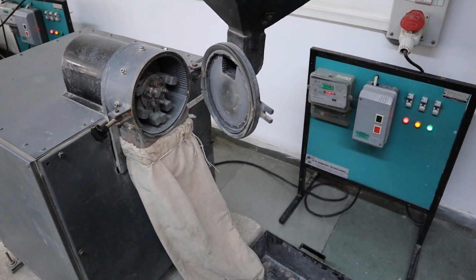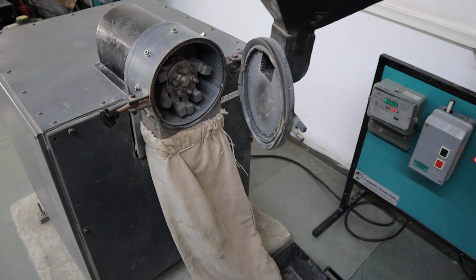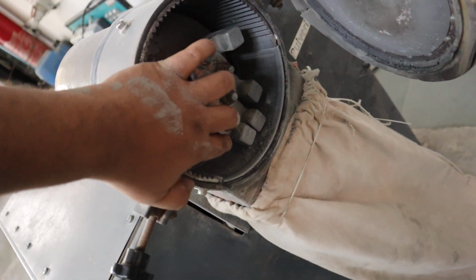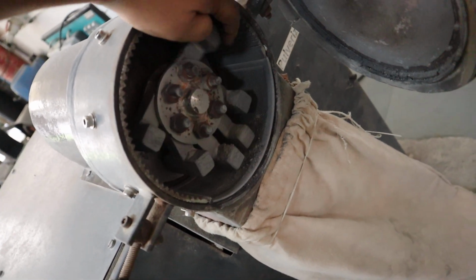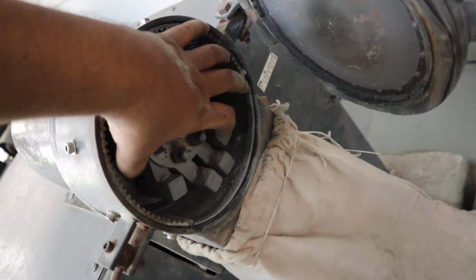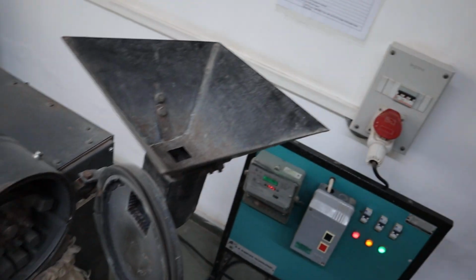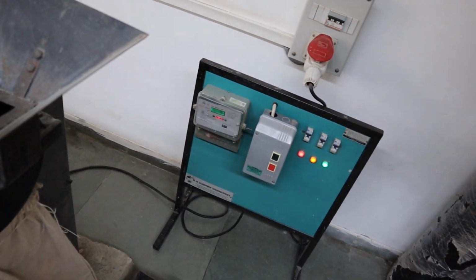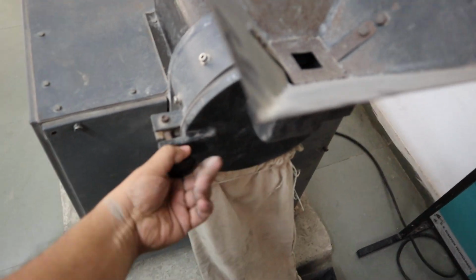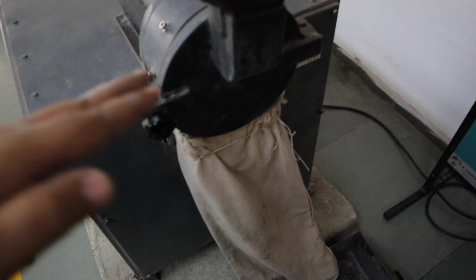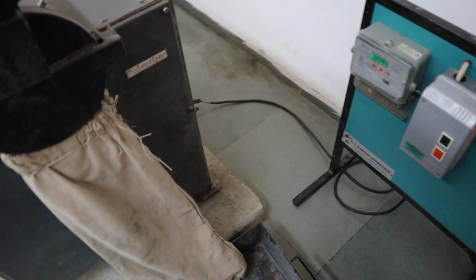And this is the hammer mill. Mainly it uses attrition and shear force to crush the material. As you can observe, there are hammers. While the shaft rotates, these hammers will hit the material, and we pour the material into the hopper. We just close the machine. While you put the material in, it goes entirely into the hammer mill chamber, and it is going to rotate at very high speeds.